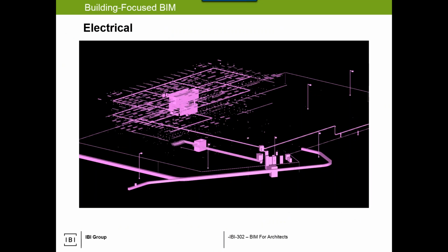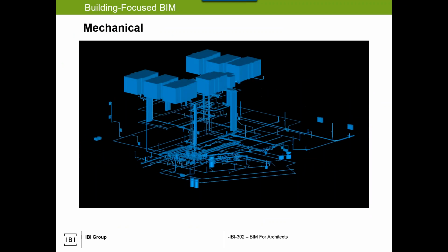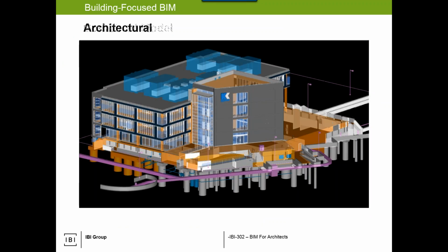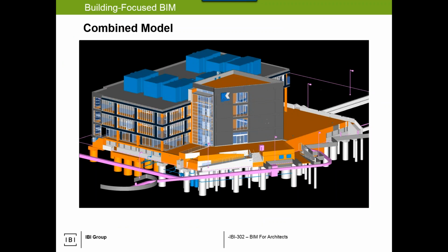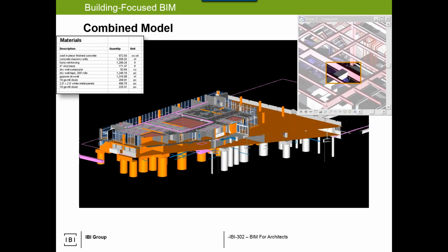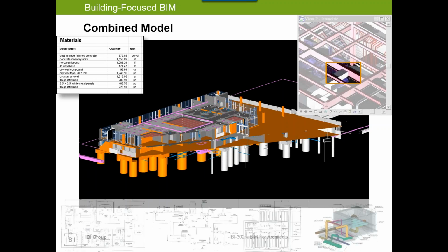Building focused BIM, it's multidiscipline BIM, so the disciplines are modeling in the same virtual space. The first three were the engineering disciplines and then architectural, and they all come together. So this session, as I said, is focusing on the architects, and the next session will focus on some of the engineering aspects. You can cut your model, slice it and dice it, get a list of content, do your clashes, and I always stress the BIM doesn't solve your clashes, it just shows you your clashes.